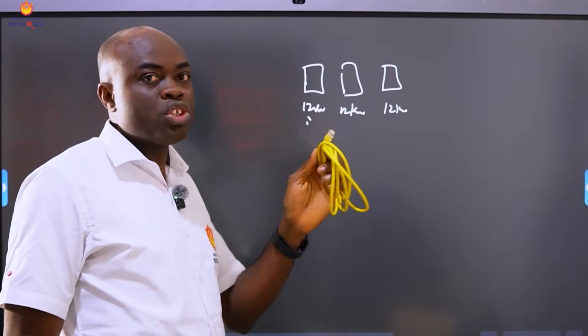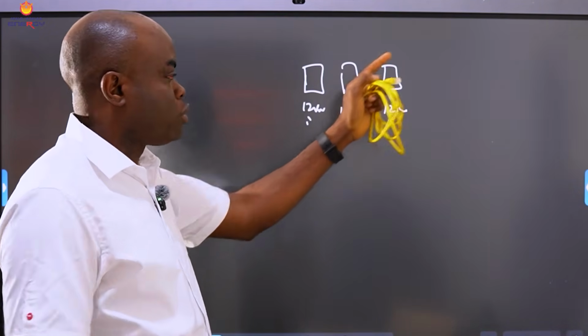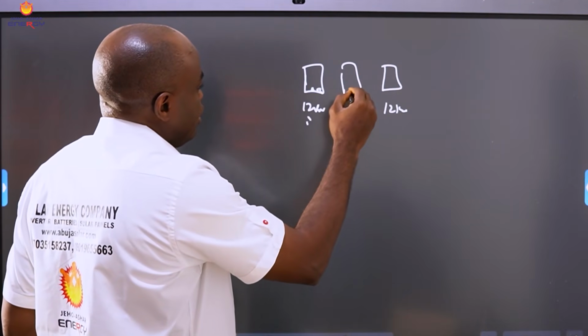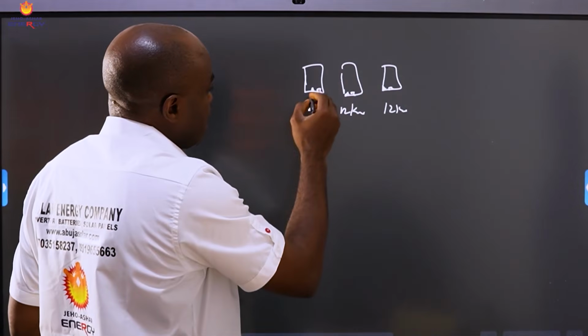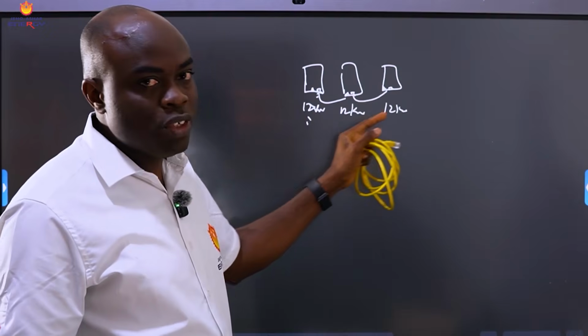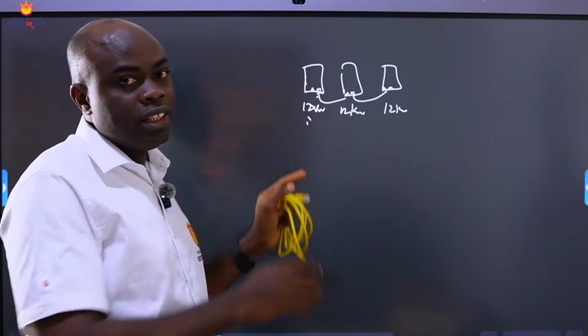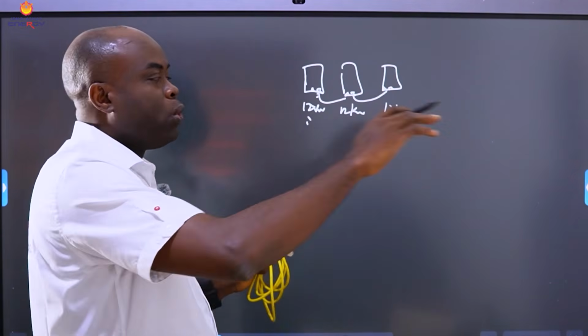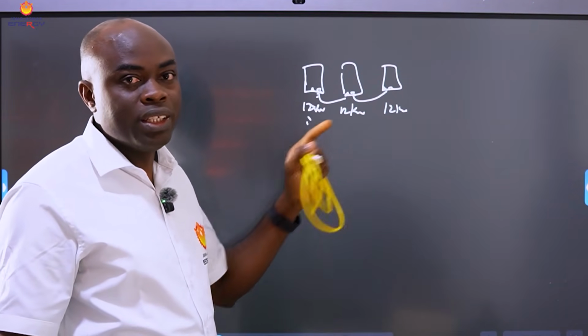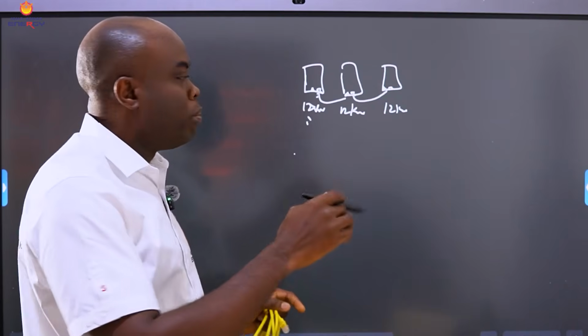You need your communication cable between the parallel ports. Inverters have A, B, A, B, A, B. These are parallel ports. So you connect to this, you connect to this. Once you have this communication cable connected, the 3 synchronize together and work as one. But without this, if you want the 3 to work as one, they won't work. The same applies to your battery also.